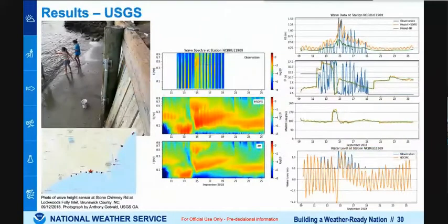So here, in collaboration with USGS, we use quick deployed gauges, which are mostly overland, for inundation and overland validation. Here on the left, the gauge bracket and coordinates are shown. In the middle, the spectral density plots from the pressure gauge data and the model results from 2 simulations on 200 and 120 meter coastal resolutions are shown. On the right-hand side, the wave height, peak period, and direction. And in the lower panel, the water level from the observations and the model.